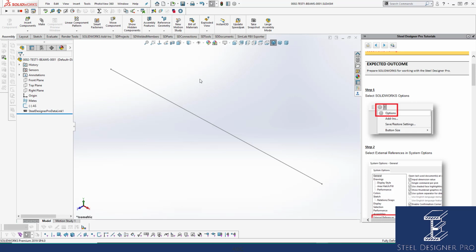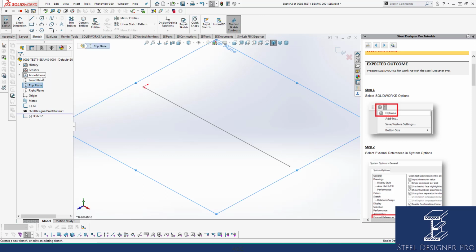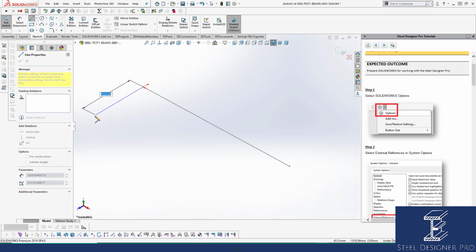Now that we have this attachment sketch in place, we can create more sketches if we want to at this level. This is a welded member assembly, which means that it can be a beam with cleats attached, or it can be a frame, it can be a ladder, it can be anything that is welded together, even a tank. So in this particular case, I'm going to add more sketches to this attachment sketch to show you how I would create a platform that can be driven.